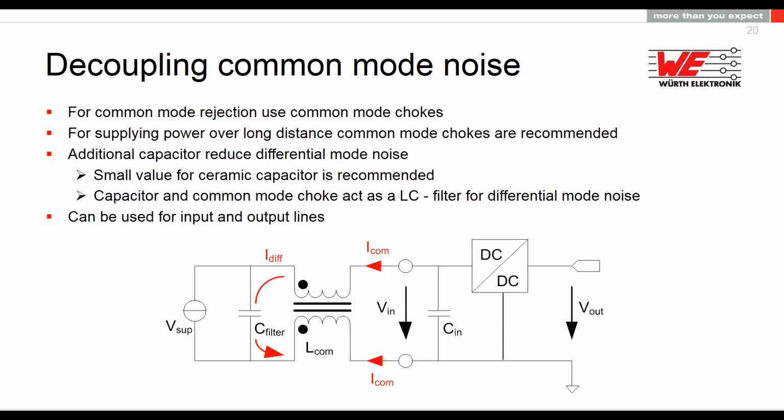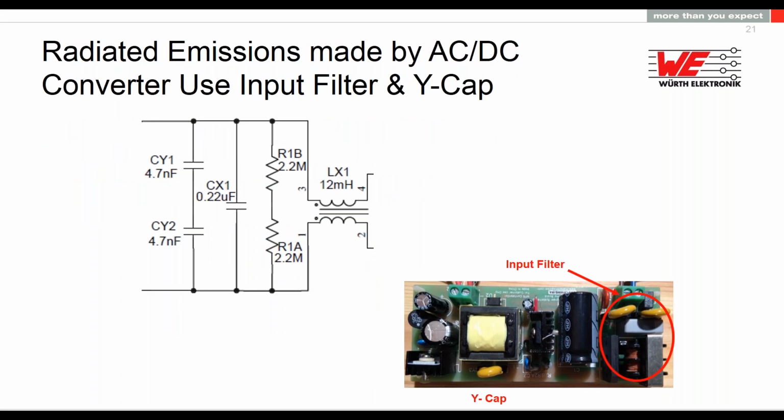If a power supply generates some common mode noise and you want to filter that, I will always recommend using a sector-wound common mode choke and using its leakage inductance. Place an X capacitor, like 10 nano, in front of the common mode choke, or 100 nano after the common mode choke, and with the leakage inductance you build an additional very nice pi filter for differential noise. With one single component you filter common mode noise, and with the same component and the 2 different capacitors, you also filter the differential noise at a higher frequency, which is always a good solution.